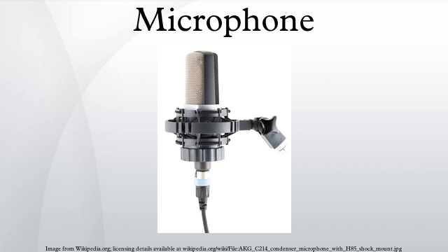Microphone windscreens. Windscreens are used to protect microphones that would otherwise be buffeted by wind or vocal plosives from consonants such as p, b, etc. Most microphones have an integral windscreen built around the microphone diaphragm. A screen of plastic, wire mesh or a metal cage is held at a distance from the microphone diaphragm to shield it. This cage provides a first line of defense against the mechanical impact of objects or wind. Some microphones, such as the Shure SM58, may have an additional layer of foam inside the cage to further enhance the protective properties of the shield.